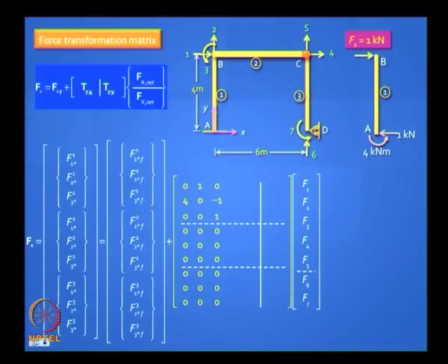I am applying this load on this structure here, only this element gets affected, elements 2 and 3 remain unaffected. So the first column corresponding to F1 equal to 1 will have 0 0 0 0 0 0 for elements 2 and 3. For element 1, these are the reactions I get. I have not shown the element coordinates; they would be 3 by 3, right. So the first item here, what does F1 star correspond to?